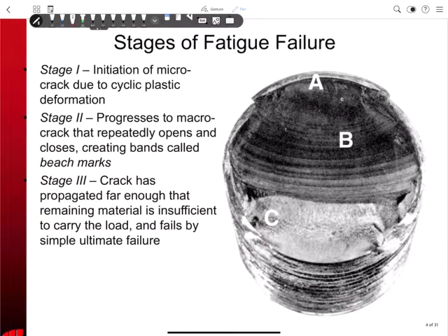All right, so stage one. These are the stages of fatigue loading. I'll do these in red. Stage one is right there: a tiny crack forms. We might even call that a micro crack. It's on the order of crystals. It's not a crack that you can see. It's a crack the size of the metallic crystals, very, very small, that forms. Now that becomes a stress concentration.